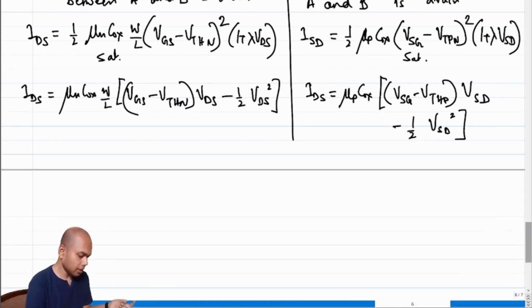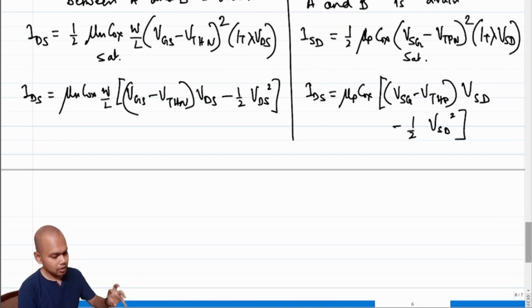Okay. Another piece of information that I should tell you before we move on is that in the literature, in some books, we tend to use these PMOS equations as negative. I mean, we tend to have negative VGS, negative VDS, negative threshold voltage in case of a PMOS equation. That is also fine, but the only key thing that we need to differentiate is the fact that sometimes in the literature, the threshold voltage is referred to as the voltage required on VGS.